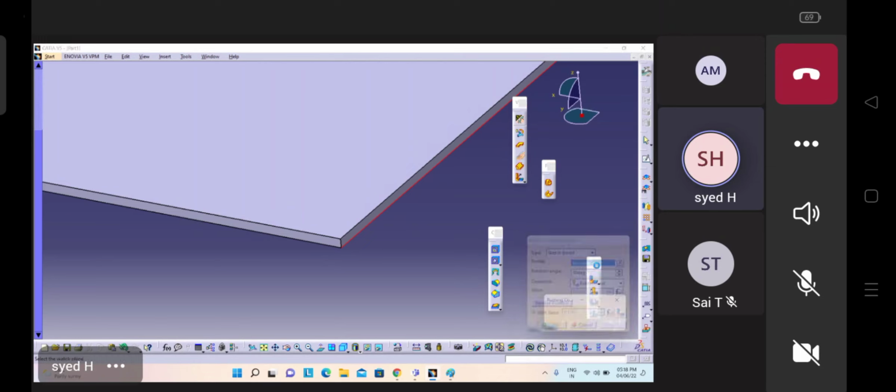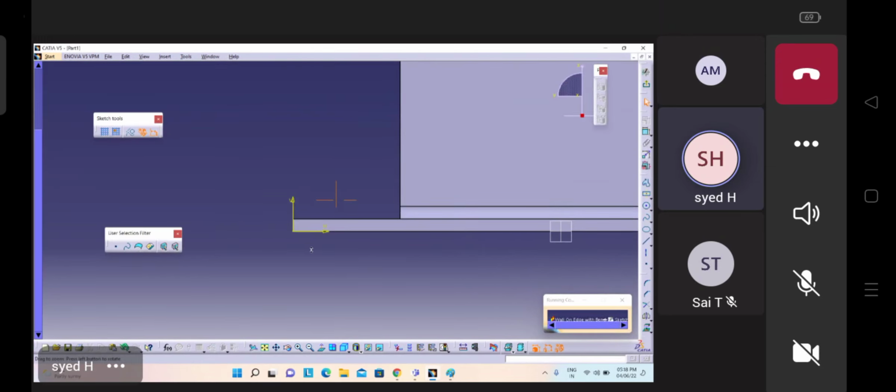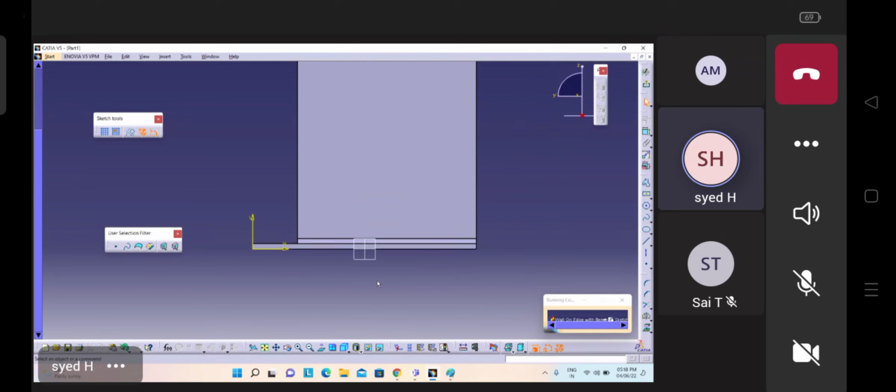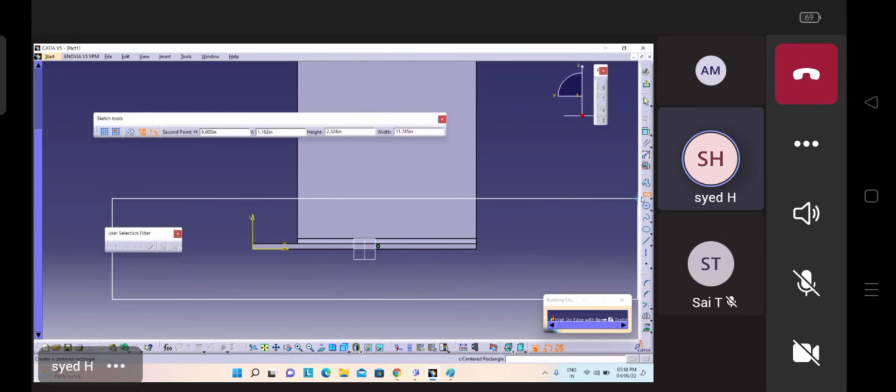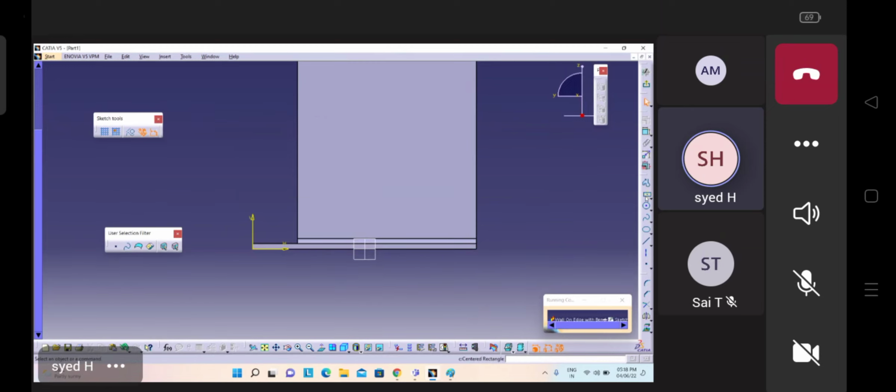It's not taken. Okay, click on this option, then select this plane face. It will enter here. We have selected the bottom edge, so the sketch should be closed and the bottom edge must coincide with the bottom. So for that reason we have to create the object. So I'm clicking on rectangle here. Not this one, go for the normal rectangle.